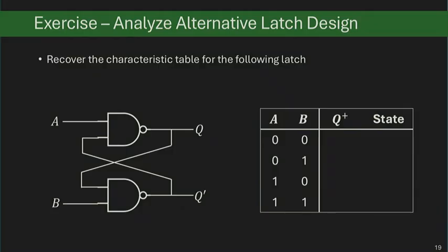And did you also find the hold case? What allows you to remember the previous state? Yes, it is. Right. 1 makes those 2 NAND gates an inverter, so they get to remember what happened before.